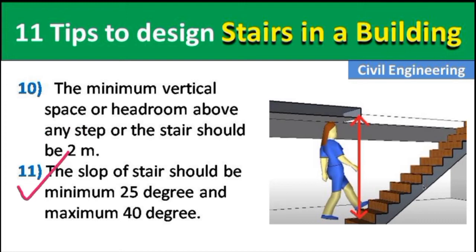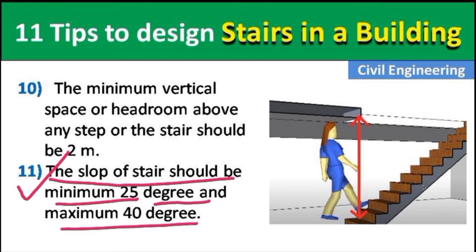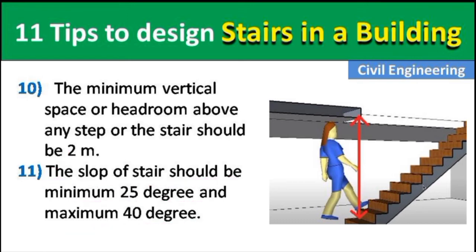Now point number 11 and the last point is the slope of stairs should be minimum 25 degree and maximum 40 degree. Okay guys, for safety and for efficient moving on the staircase, the slope of the stair should be between 25 degree to 40 degree.